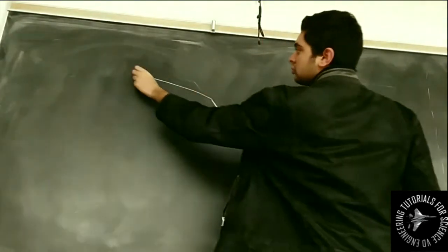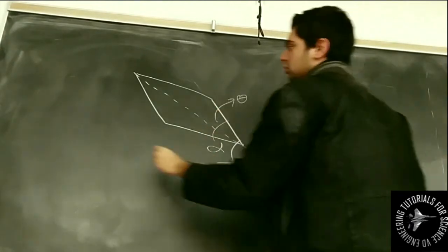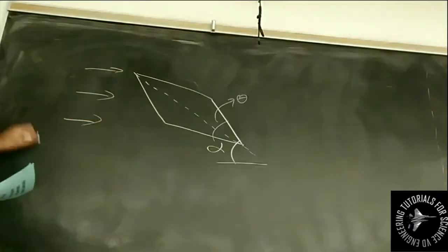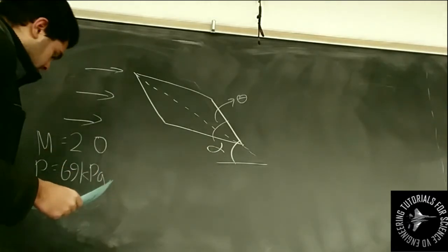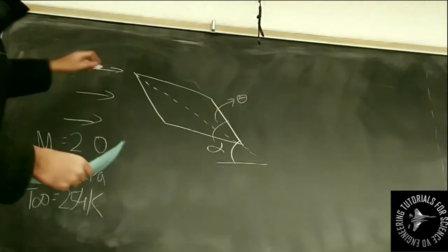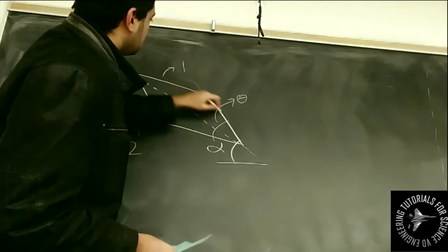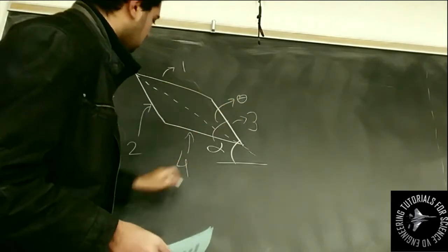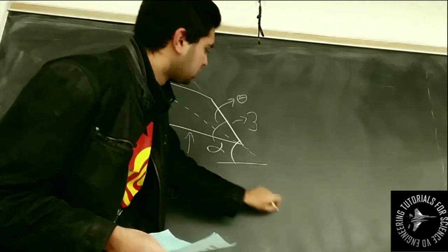So you can see my drawing over there. I have an airfoil, and then from that I can then calculate my angle of attack and airfoil angle that's fixed, and then from that I can get my Mach number and my pressure value. It's all given to you in the problem. There's temperature given as well, just in case we need it for CFD validation in part 2. I'll label my faces as shown over there, and the goal is to calculate the pressure values.